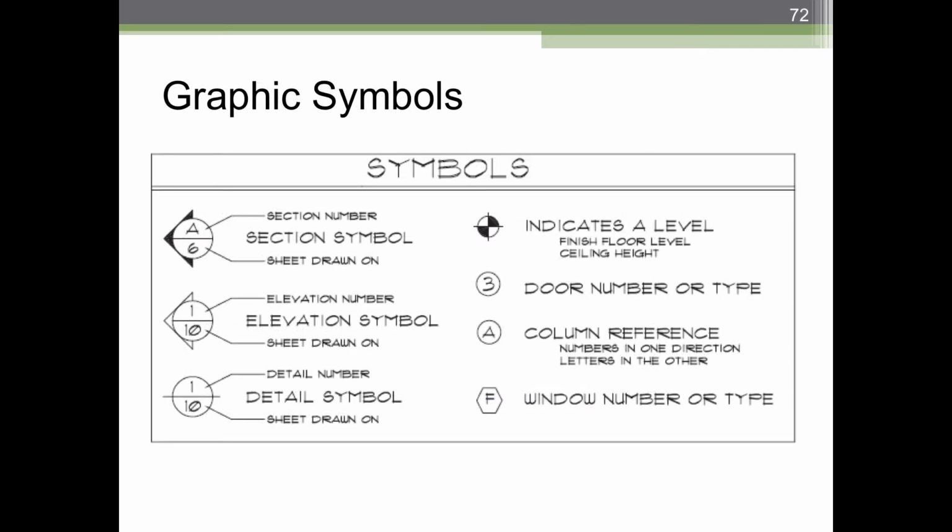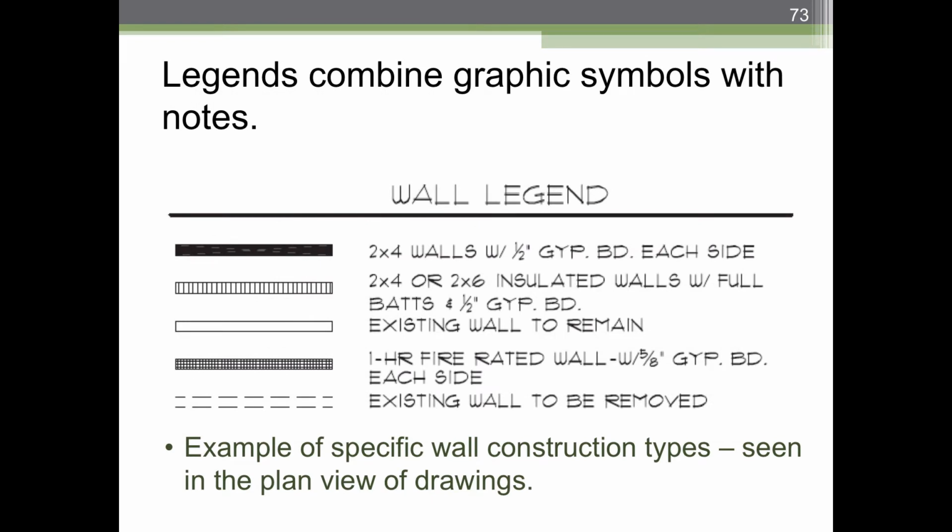Okay, and graphic symbols, again, Revit is going to help you out with this, but you should be aware that a lot of those symbols, the section symbol, for example, that we use all the time, will fill itself out for you. I've noticed sometimes I see drawings where there's an empty symbol and it just looks funny to me. So be aware that if you're using that symbol, it's expecting you to drag that drawing onto a sheet in order to fill itself out. So don't use it if you're not going to drag it onto a sheet.